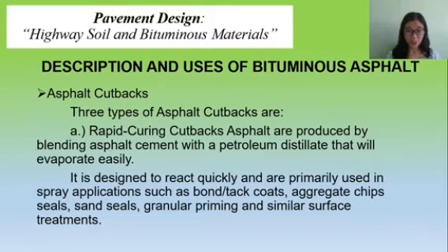And lastly, we have the rapid curing cutback asphalt. It is produced by blending asphalt cement with petroleum distillate that will evaporate easily. From the word rapid, it is designed to react quickly and is primarily used in spray applications such as bond or tack coats, aggregate chip seals, sand seals, granular priming, and similar surface treatments.